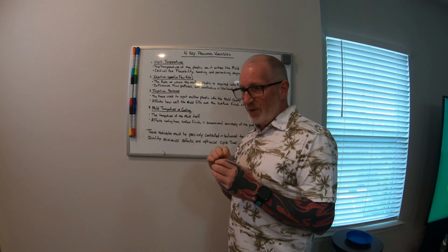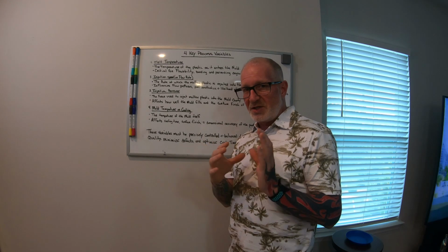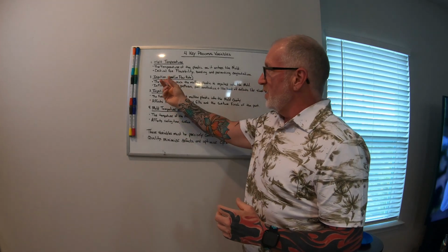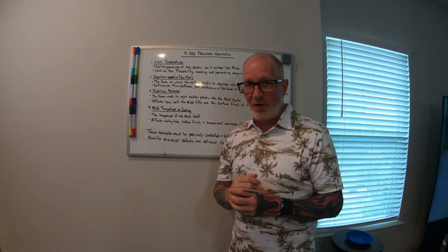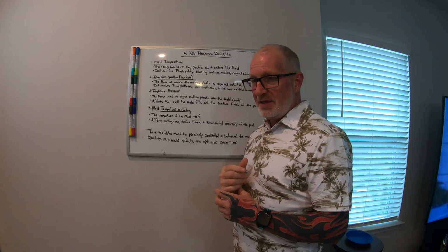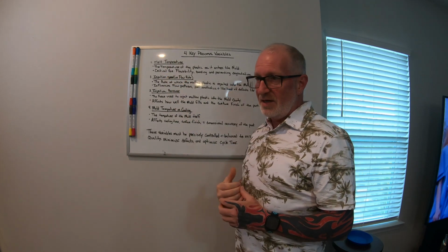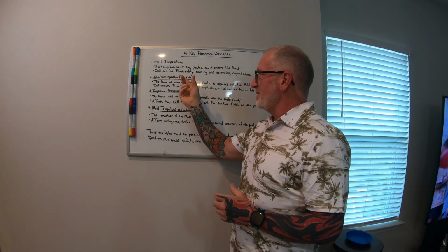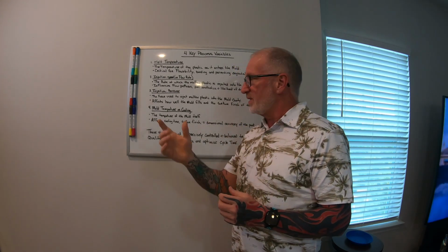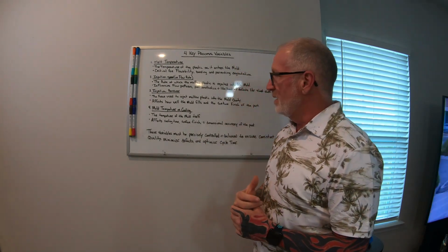As you're filling it, you're adding your shot size until you get the part to where it is almost filled all the way out, and then that'll tell you where you want to be as far as your flow rate. Remember on this flow rate too though, if you have this setting, you could go to any other press that is the same size tonnage press, and you can put that same flow rate into another press and basically run that part on another press with almost the same process.